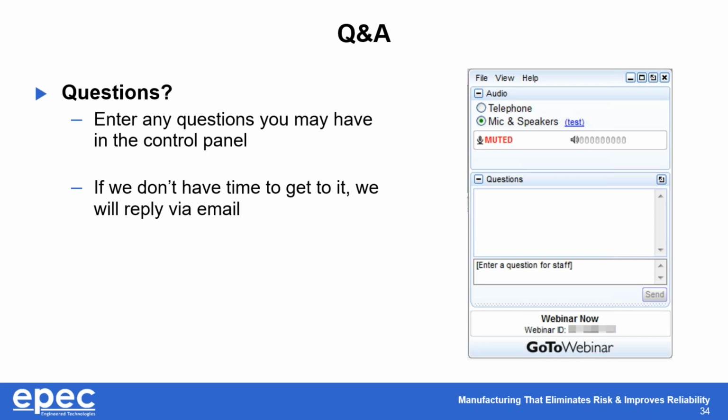Third question is regarding ferrites. Can ferrites be used on flexible circuits? And the answer is, in general, yes. Not overly common, but I have in prior history manufactured flexible circuits that ultimately have a ferrite inserted onto them.